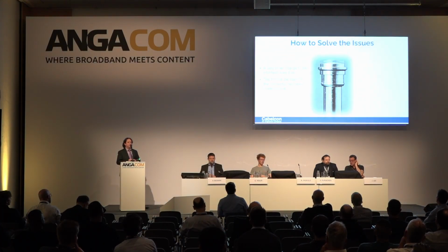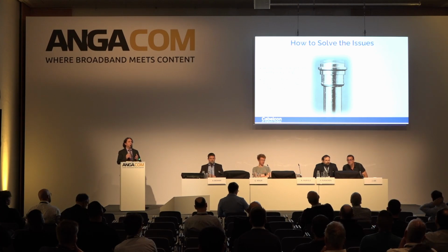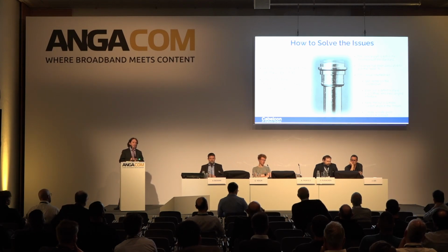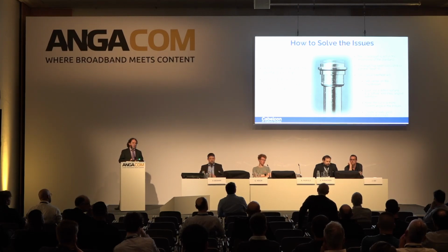Through several years of experimentation and looking at various solutions, a very small change to that front port of the F connector can have a big impact on how we can work with all these different sorts of variations in the F ports out in the field. So the front insert has been made conical, and this helps to self-center the F connector on the various ports that it's seeing, and it can even help to overcome some of the defects that we're seeing as well.